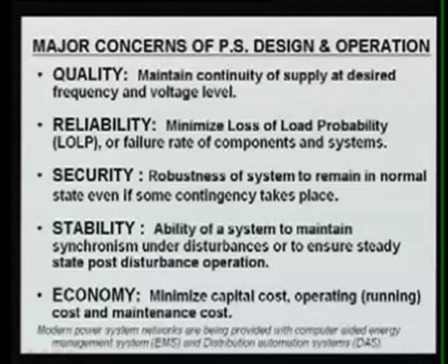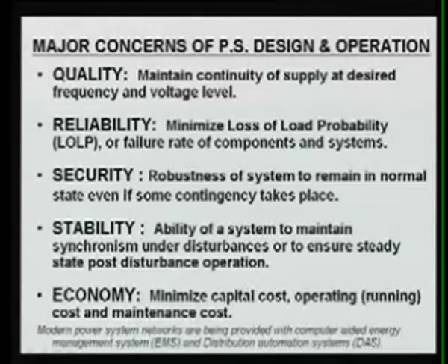The fourth concern for power system design and operation is stability. As you know, stability is one of the big concerns in an AC power system. It is the ability of a system to remain in synchronism under disturbance or to ensure steady state post disturbance operation. We have to operate our power system in a secure, reliable, and also stable manner.